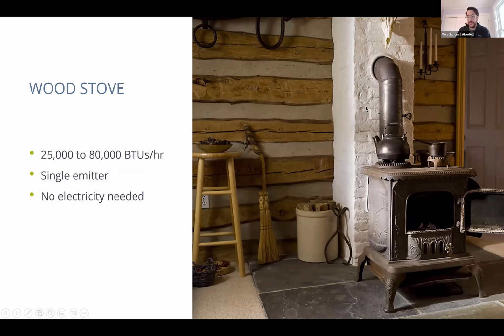So that air is going to rise up, and it's going to displace or push the air that's already up there away. So what ends up happening when you have a wood stove is it does create these natural convective loops inside of the room, which helps extract more heat, or more energy, from that actual wood stove or through the firebox inside of it.